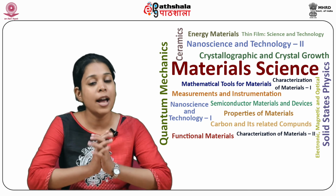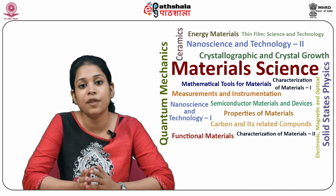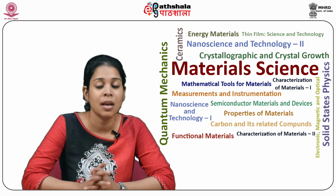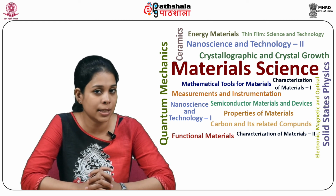For high frequency applications up to about 5 megahertz, nickel zinc ferrites are useful, while for frequencies up to 100 kilohertz, manganese zinc ferrites are preferred due to their high permeability.